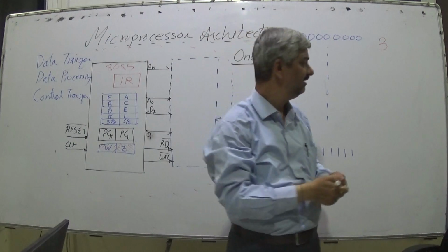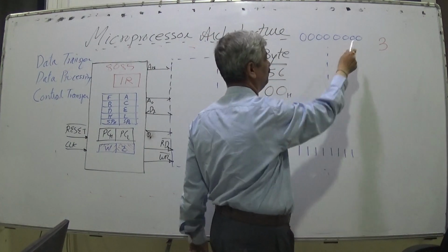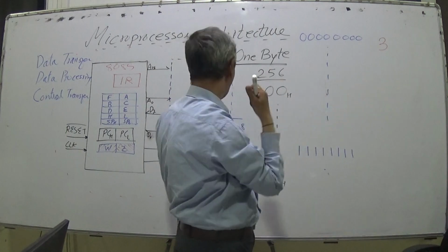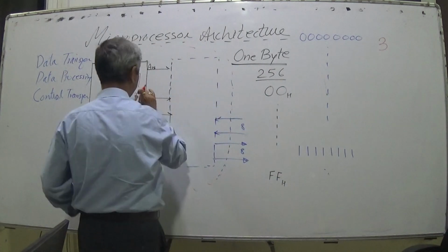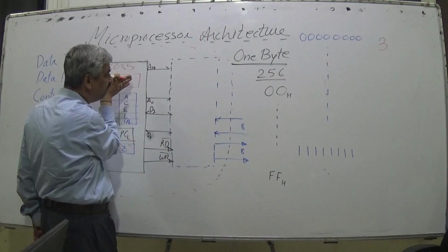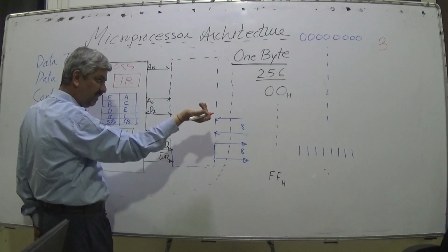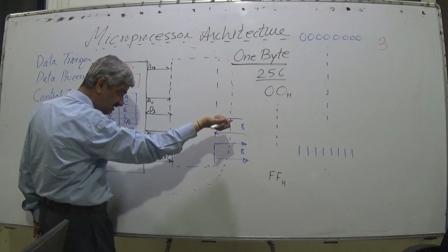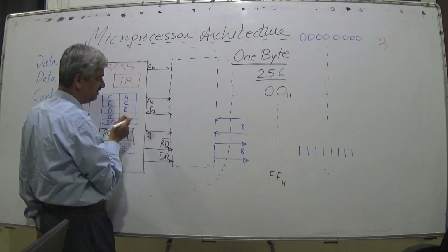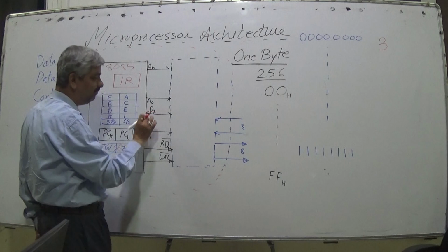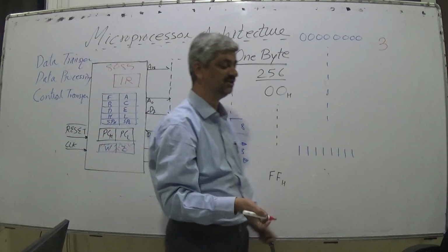Like that, when the microprocessor receives a combination of all zeros as a response to a memory read cycle from address 0, to be fetched as an opcode, as it is a fetch cycle, whatever is received is treated as an instruction.